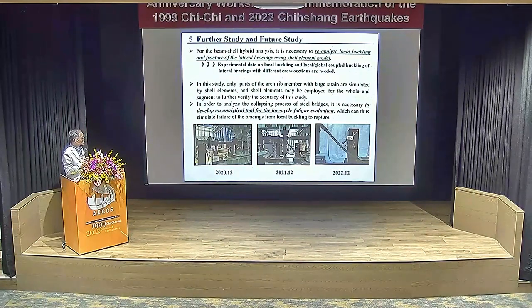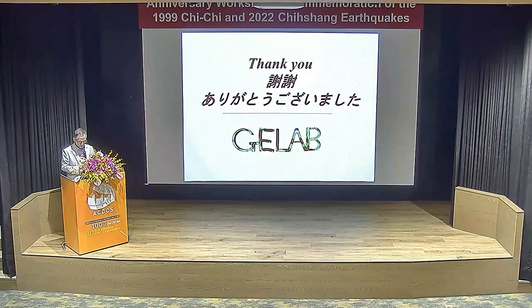Yeah. And also, in order to analyze the collapsing process of steel bridges, it's necessary to develop an analytical tool for low-cycle fatigue evaluation, which can then simulate failure of braces from local buckling to fracture. We are doing some tests on braces these years, and we will summarize the results and perform analysis to check our method. That's all from my presentation.